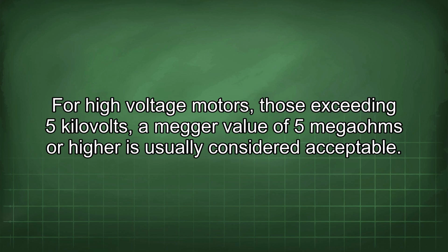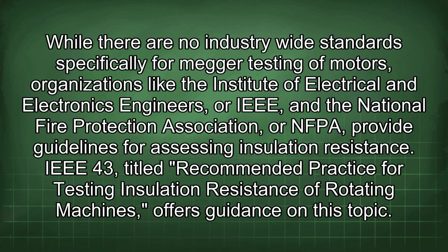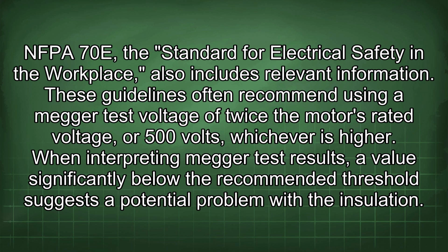considered acceptable. While there are no industry-wide standards specifically for Megger testing of motors, organizations like the Institute of Electrical and Electronics Engineers, or IEEE, and the National Fire Protection Association, or NFPA, provide guidelines for assessing insulation resistance. IEEE 43, titled Recommended Practice for Testing Insulation Resistance of Rotating Machines, offers guidance on this topic. NFPA 70E, the standard for electrical safety in a workplace, also includes relevant information.